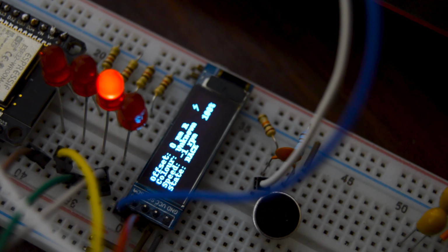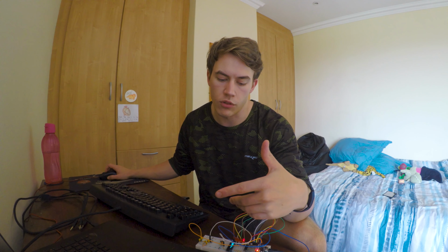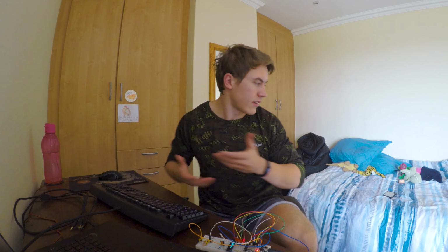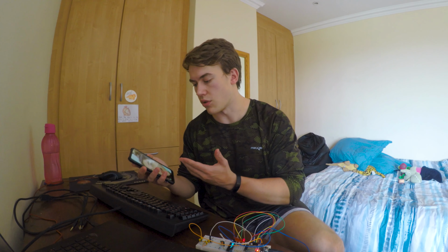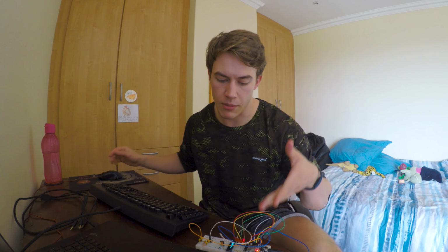Then the display is this little OLED screen here, which I'll intersperse some close-up footage of so you can see. I coded it with, I think it was the U8g2lib library, which is really cool and useful, and you can do a lot with just a small 128 by 32 OLED screen. It's really cool to work with an OLED screen and see how big devices like your cell phone work on exactly the same principle. It's just a huge grid matrix that you can draw on, and obviously a lot more complicated, but this grid matrix is the same as this little grid matrix here, and it was cool to play with, and even if you just use a library, it was cool to master.